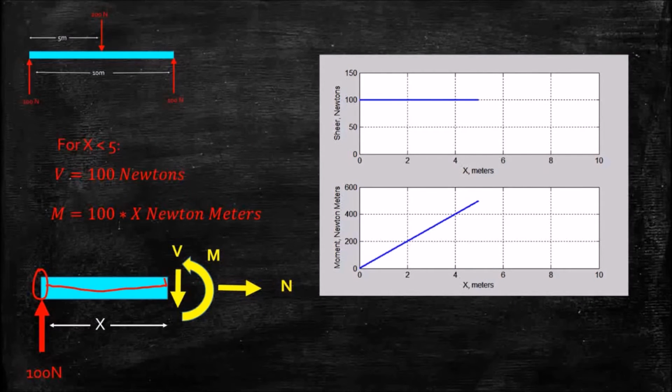And our shear force is a constant positive value, and we look at the moment, and this moment has a constant positive slope. As it turns out, we can find the shear force by integrating the load across that section, and we can find the moment by integrating the shear force. But we'll go into those details in another video. I'll just mention that for now as a way to check whether this makes sense. If my shear force was 0, how could my moment be changing? But that constant positive shear force results in a constant positive slope on the moment.